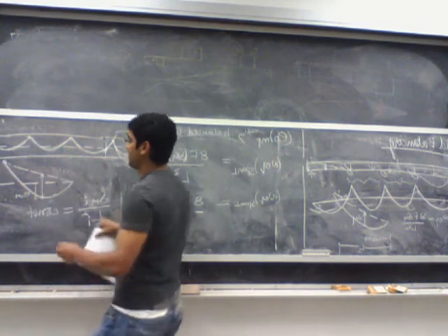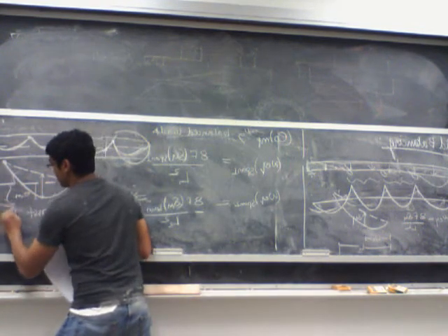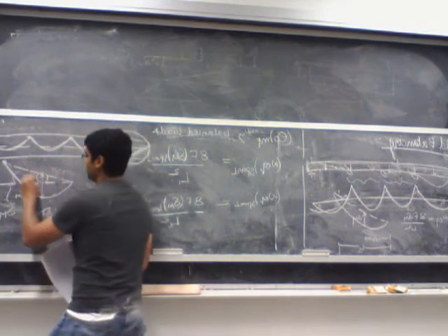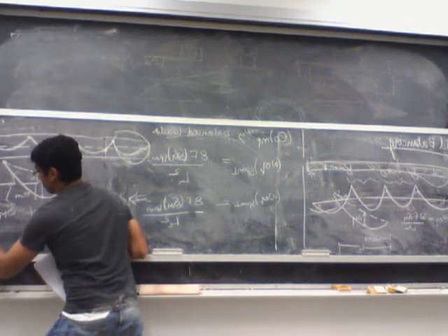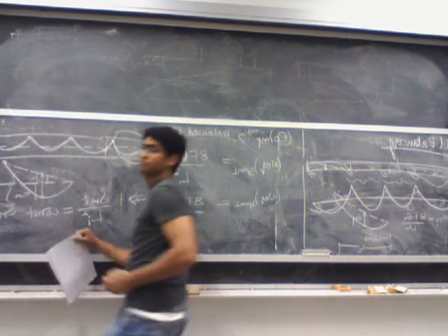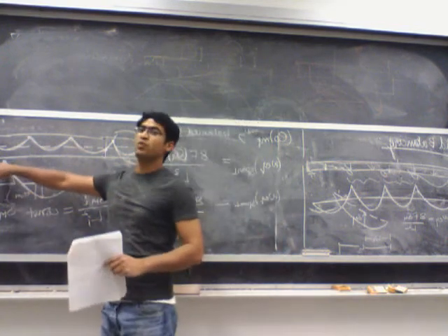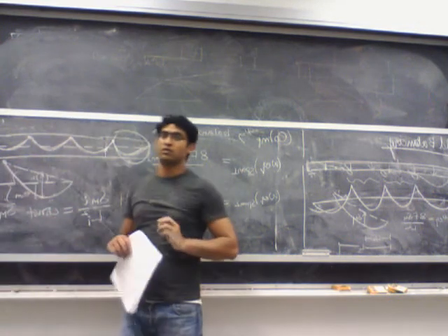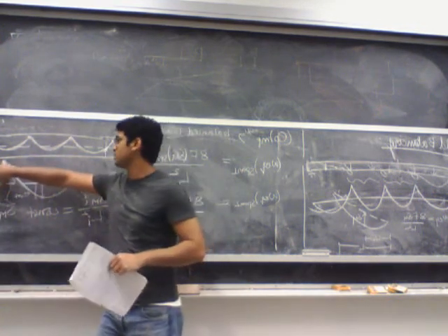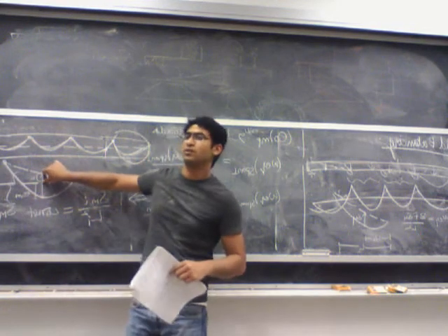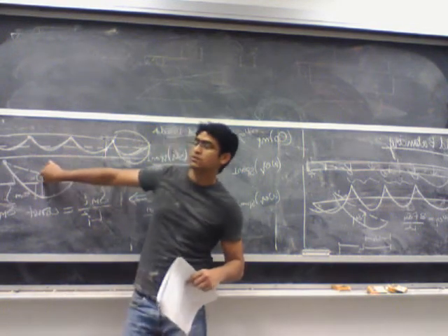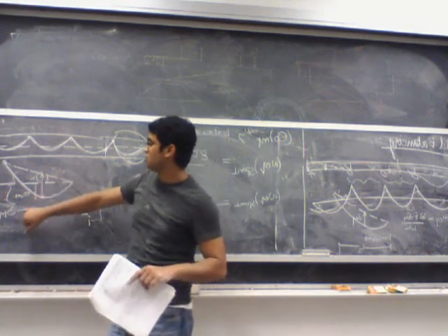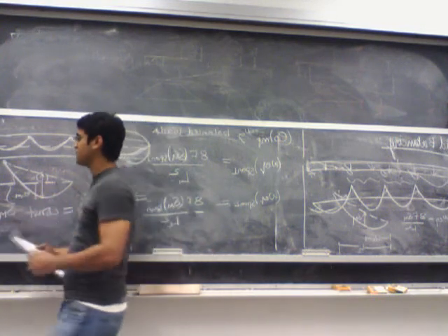And this total height is delta M. So for this case, my delta M is nothing but this small height, let's call this h, plus E naught m. The good thing is, if this point is fixed, let's say as in the problem assignment, let's say it's 6 inches. Since you have already maximized this height, you know this is 6 inches, so you know this is actually 3 inches, because this height is always calculated at the mid span. So this is 3 inches, this is E naught m, so I have delta M equal to 3 plus E naught m.